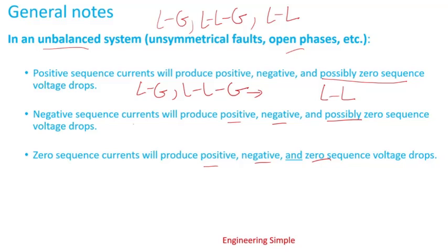I hope this video helps provide a good understanding of how to use symmetrical components to calculate sequence currents due to imbalance, that occur due to single phase loading, for instance, or an open phase, in a three-phase system.